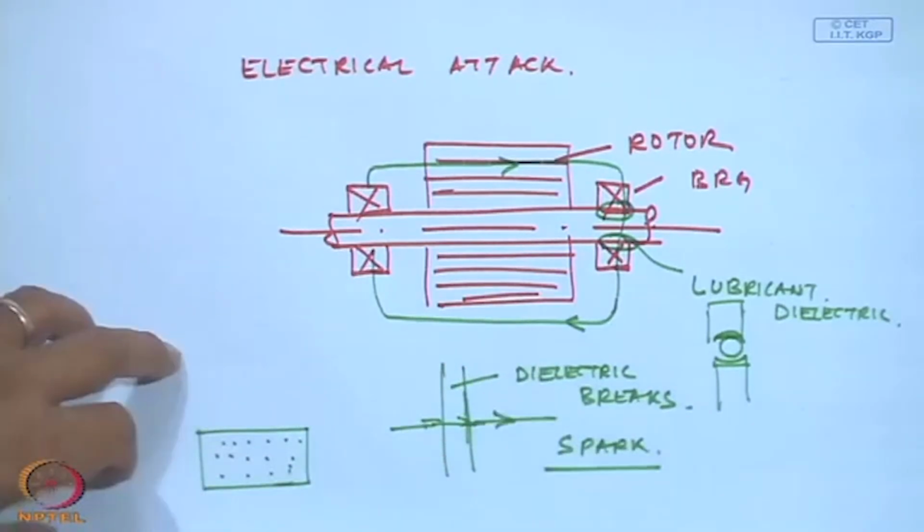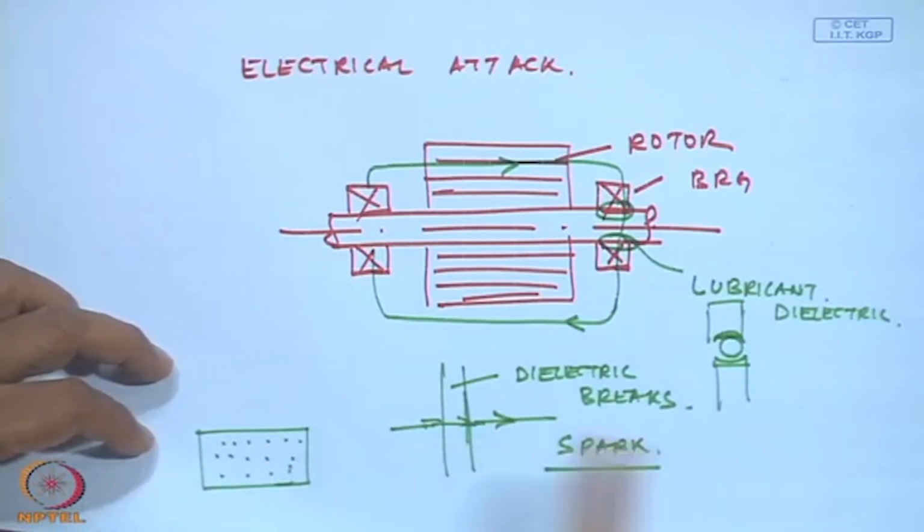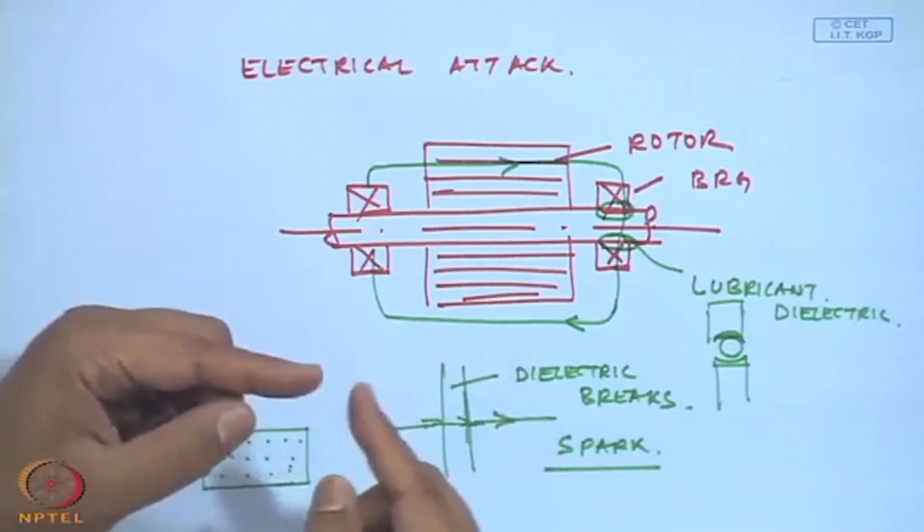So, one has to be very careful when designing electrical motors, or particularly when you have high voltage electricals in your machinery, wherein there are parts with lubricant and there is a discontact. We may not get a voltage as we measure, but when they are going at high speed, because of this EMF, if the grounding is not proper, we will get sparks, and these sparks are responsible for erosion, like an EDM, like an electrical discharge occurring. In fact, people use these high voltage sparks in electrical discharge machining to machine surfaces, but here the same EDM may be harmful to our machines.